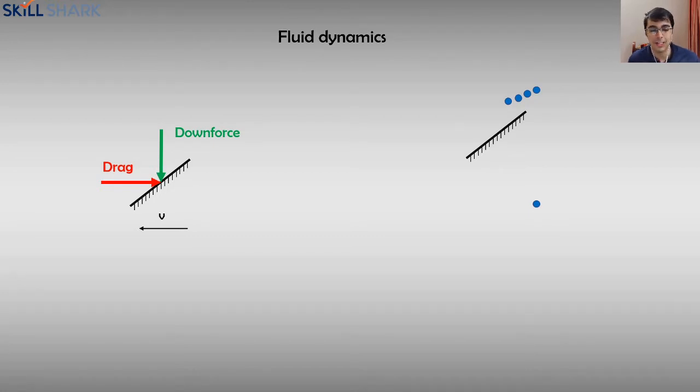So effectively, all these particles hit the plate, and this continually happens based on how separated that flow is. But what we consider here is laminar flow, so it's all uniform in terms of distribution, at least up till the plate. Because all these particles collide with the plate, you have an effective force being applied on the plate. So the particles effectively deflect in this way, and you have an effective force acting on the plate. Now that can be resolved into a downward force and a horizontal force towards the right, and that's what is resolved as downforce and drag.